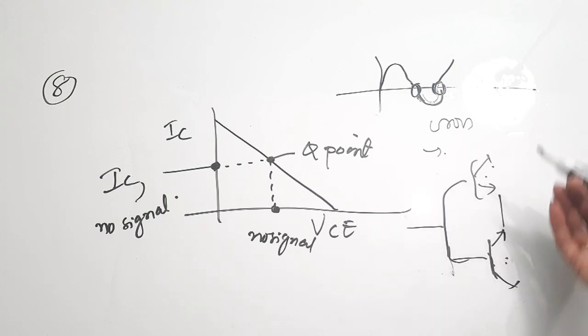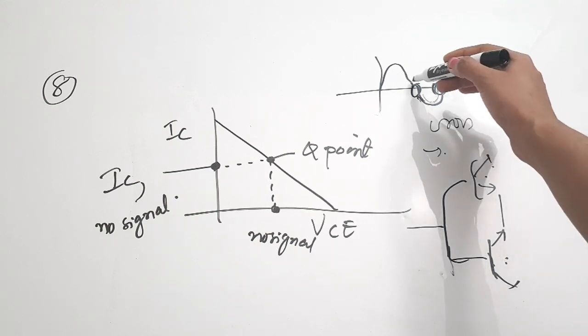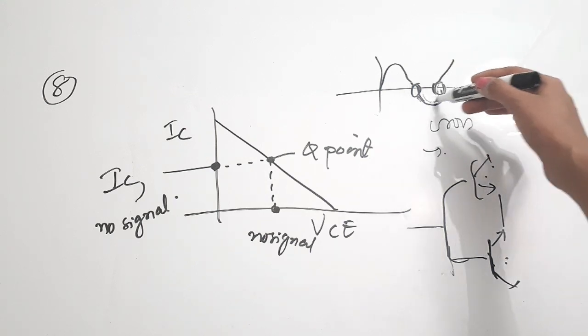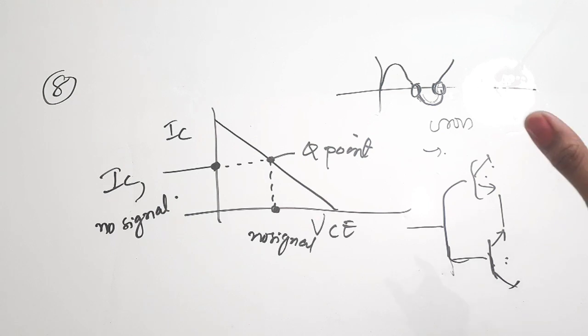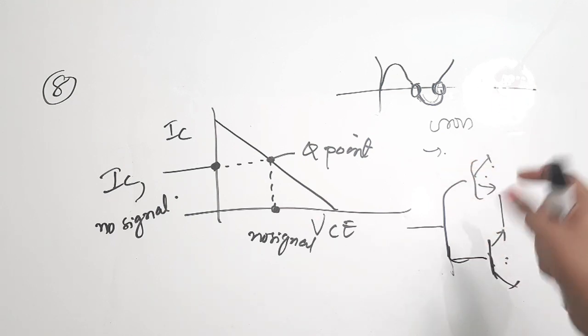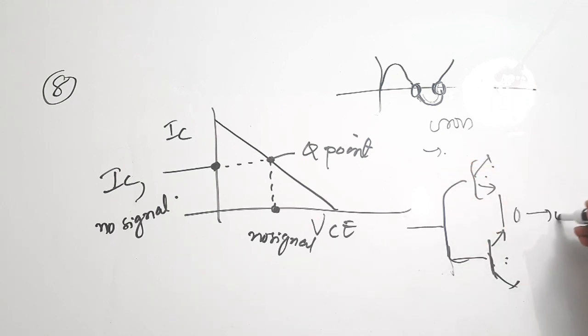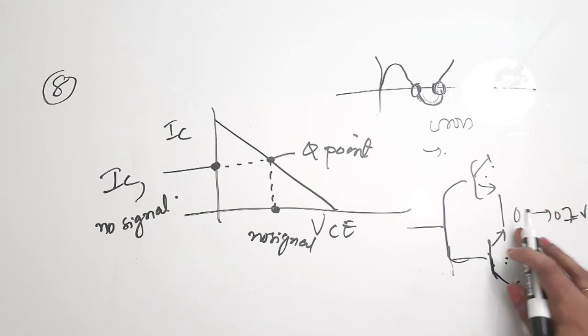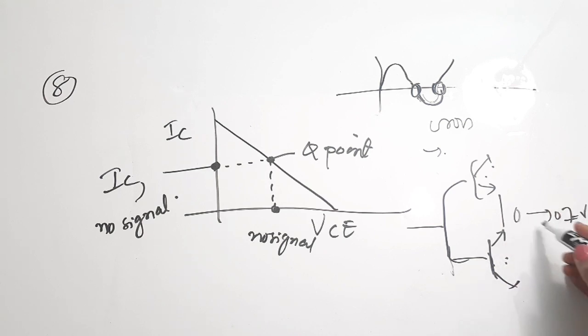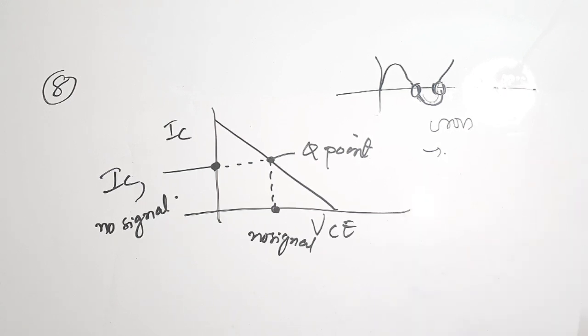So due to this problem, when the signal is crossing the zero line, there will be some delay to start the output waveform, because this voltage from 0 to 0.7 is not actually producing any output, since only when 0.7 is reached, this transistor will start conducting. So that is the reason. Anyway, just watch the video on crossover distortion also. You'll get a very clear idea.